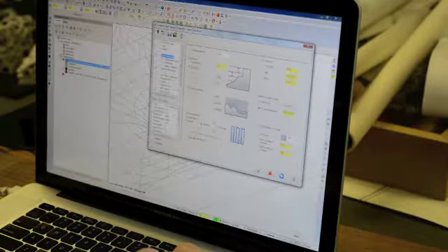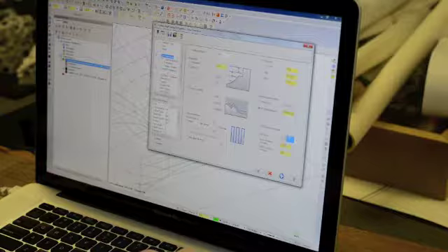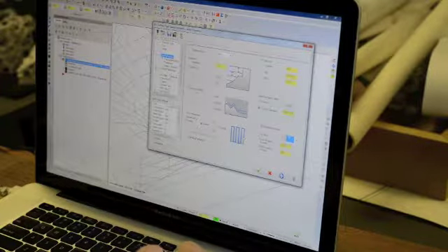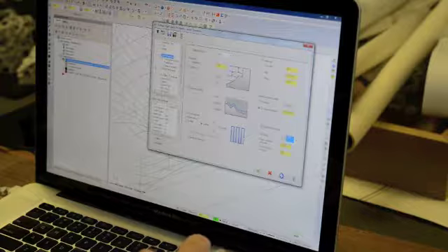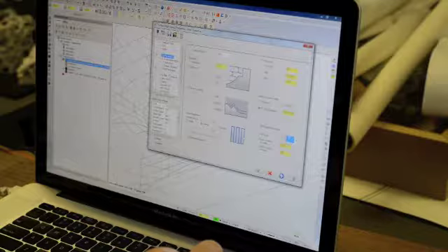And then over here, these things we have always left as the defaults. Same thing with the XY step over, and same with this. Over here though, the tip compensation we always leave at the actual tip, and then stock to leave on walls. When you're rough cutting, you can leave a small amount of material on, and all that is doing is reducing the amount of time that you're down there milling, because the finish passes will clean up this little bit of material.